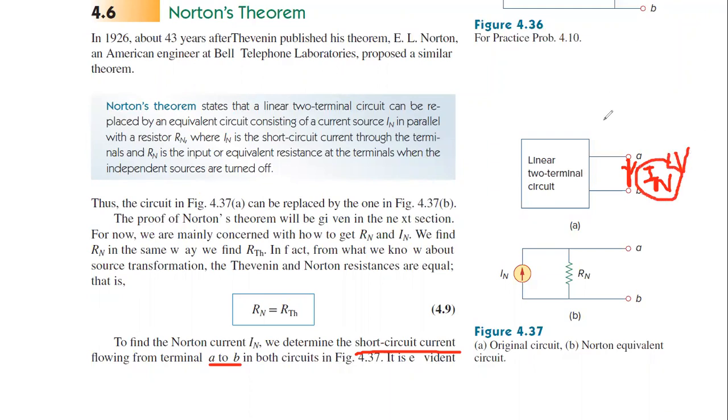Over there, you can simply open circuit your element. If you connect the DMM over here, you can get the voltage on the display. But here, for finding the current, you must give some path between the output terminals, or between the open terminals. Then only the current will flow. You can easily measure the flowing current through the connecting wire. So that is about finding this IN.